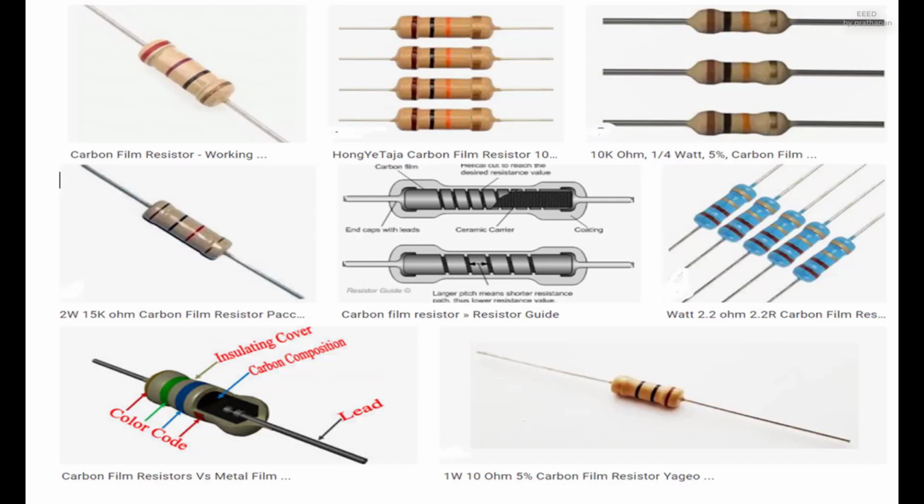Carbon film. Carbon film resistor with exposed carbon spiral, Tesla TR212 1K ohm. A carbon film is deposited on an insulating substrate, and a helix is cut in it to create a long, narrow resistive path. Varying shapes, coupled with the resistivity of amorphous carbon, ranging from 500 to 800 μΩ·m, can provide a wide range of resistance values.